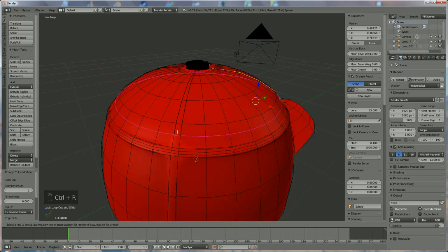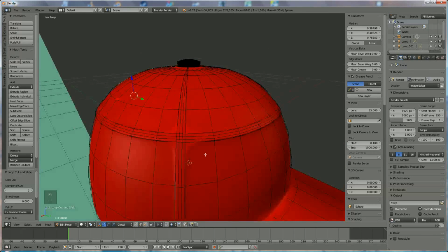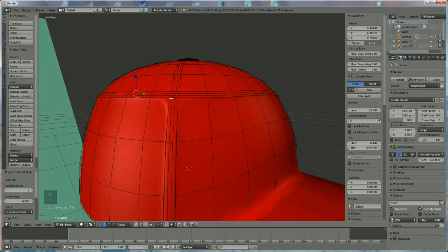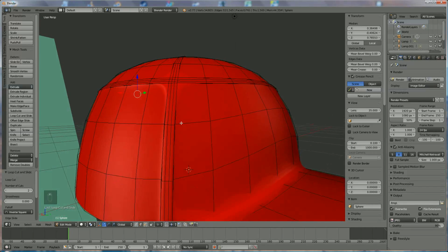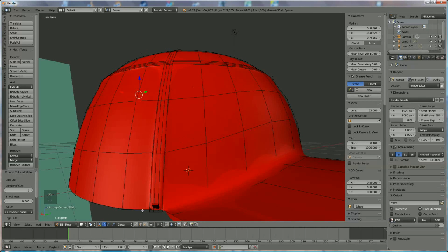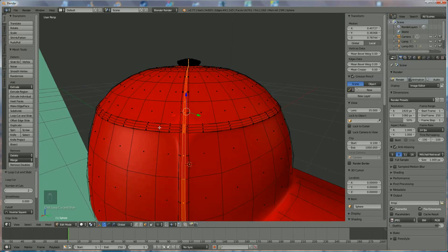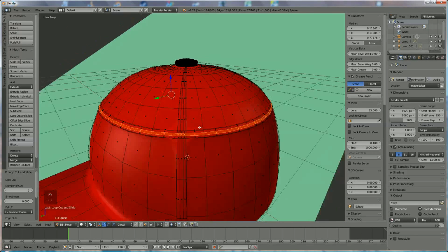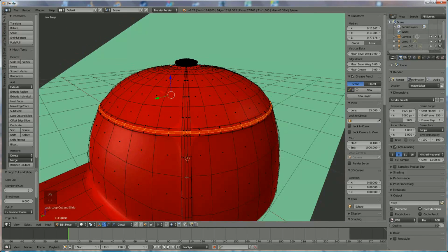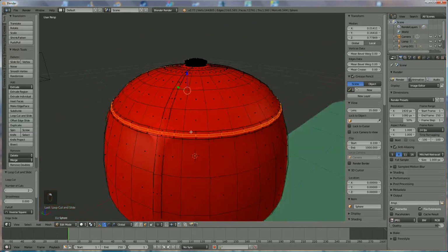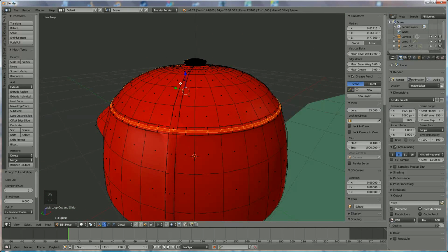And the last one, Control R, roll on it, double click on it, escape. Now this is the difficult part, to select everything, not the top. Okay, so we're going to do the same, face selection over here, hold down the Shift Alt button, click on that one, Shift Alt, click on that one, Shift Alt, click on that one, Shift Alt, I've forgotten one.